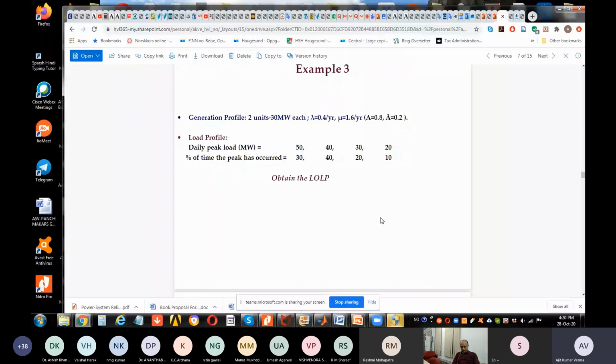So the important thing is to identify the criticality and the impact of the failures of units, components, subsystems on the system. So you do a criticality ranking, and why do you want to do it? Because you want to initiate measures to make the system more robust and more reliable so that it doesn't fail.